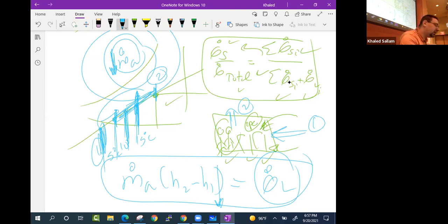And one final thought about this is that in order to have the exit at 2, we send the flow coming in at low temperature. We don't want to hit those people with 5-degree air or 10-degree air. That's too cold for them. So that's why you always see diffusers, right? In the inlet duct, it needs to be a diffuser that sends the air away from the people, sends it into the room before it cools down the people.